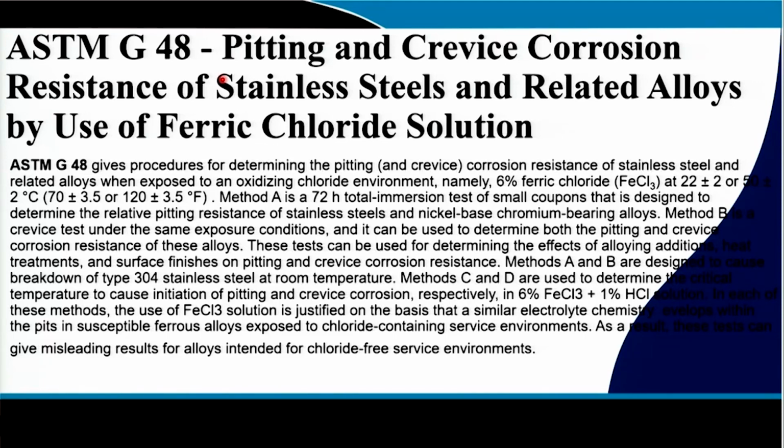When we discussed pitting and crevice corrosion, particularly pitting corrosion, we saw that if you would like to know the pitting corrosion rate by measuring the weight change of the component as a function of time, the weight change is not really significant in pitting corrosion, but the problem is the propagation of the pit.